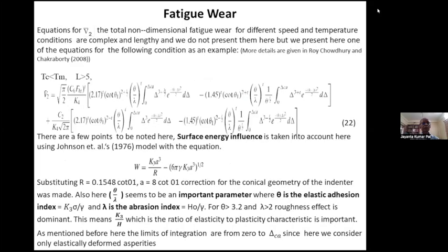Now, the equations for V2 bar, that means the non-dimensional fatigue wear for different speed and temperature conditions, are complex and lengthy, and they are available in the paper by Roy Chaudhary and Chakravarti.